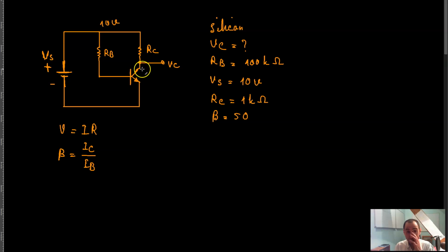And then what that means is that then, because the collector current in this scenario is basically set, there is some predetermined current flowing through your collector, meaning that there is a predetermined current flowing through this resistor as well, because this resistor is basically in line with, or in series with, your collector current.